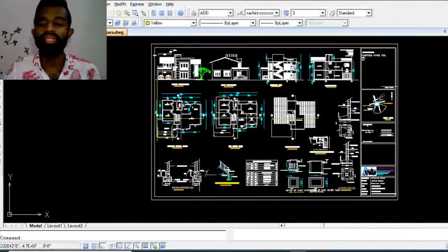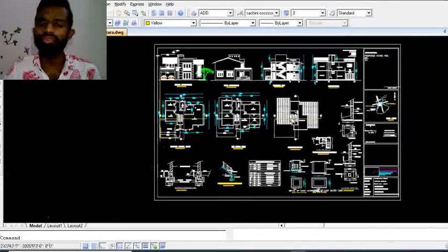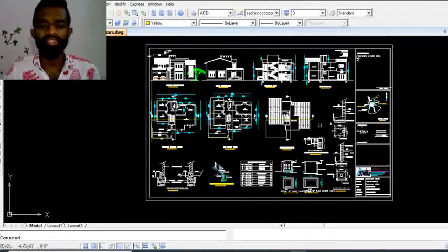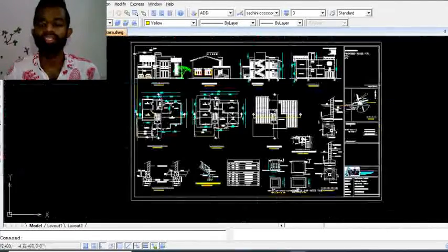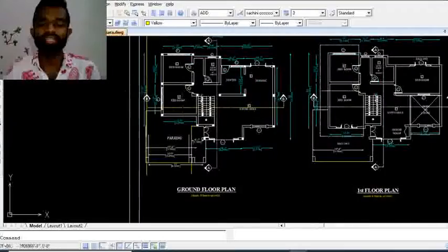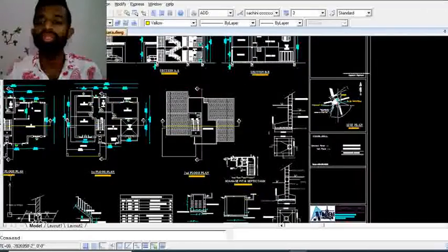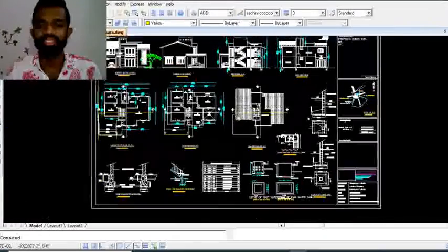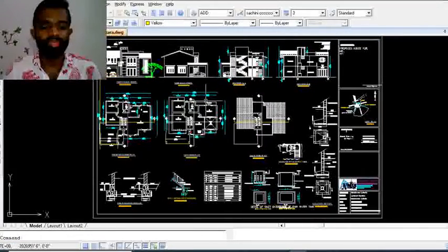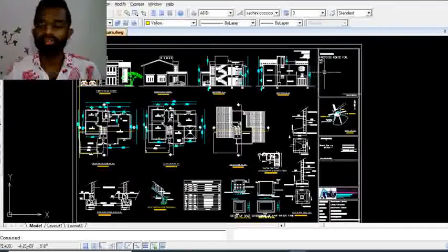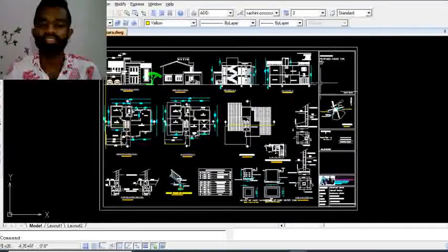the architectural drawing will be developed by an architect. So how does he develop this? He has to discuss with the client, and the client needs to reveal his or her requirements, and according to his or her requirements, family conditions and available land, the architect will draw this architectural plan according to the local authority guidelines. So first of all, you need to develop this architectural drawing, and you need to get it approved by a chartered architect and a chartered structural engineer.